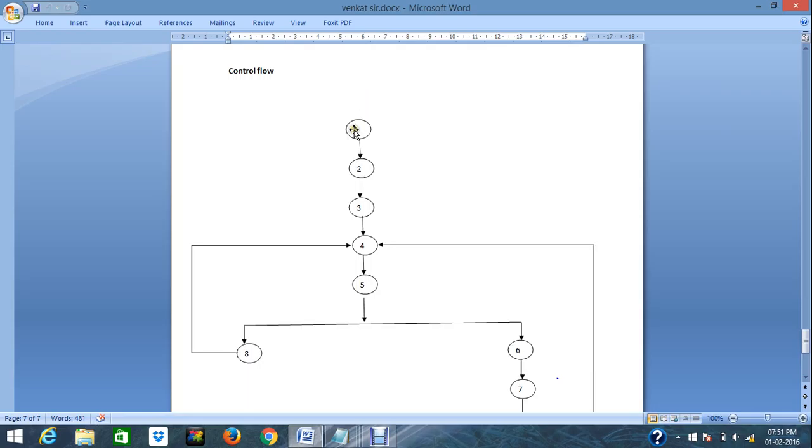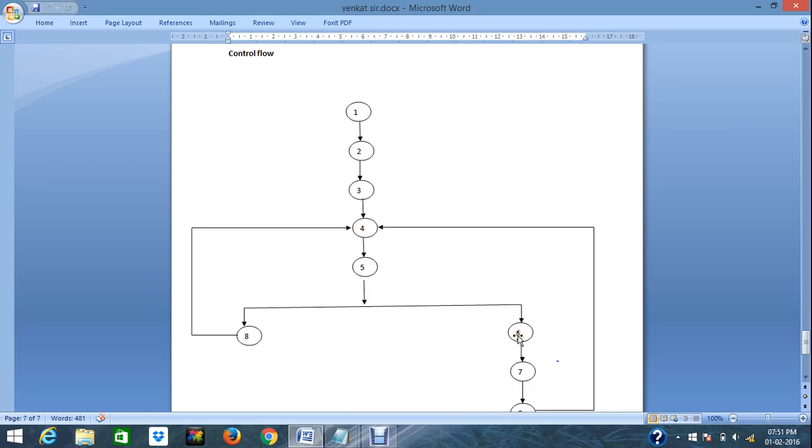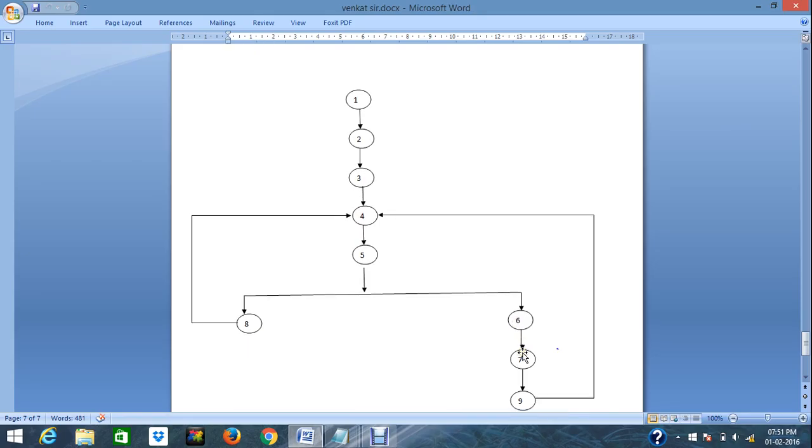It's a control flow. Control flow is as brake applied, which increases brake fluid pressure, and next the speed of the individual wheel is sensed by the sensor, and the comparison of rotational speed of individual wheel, and if any lock is detected, it directly goes to activate hydraulic valves, which cause brake fluid pressure to reduce, which will increase the speed of wheel. If not, it will reduce the speed.